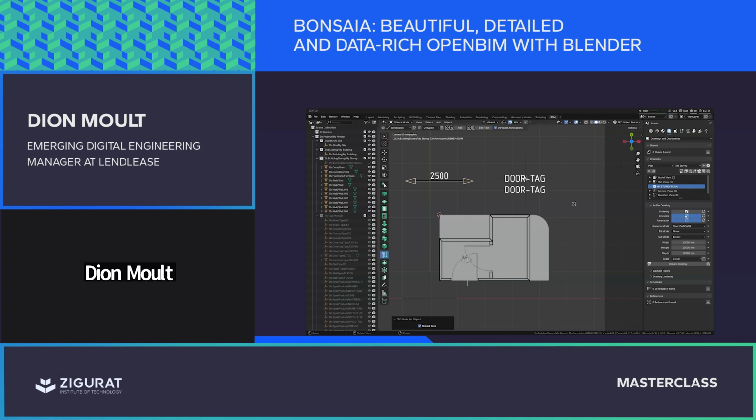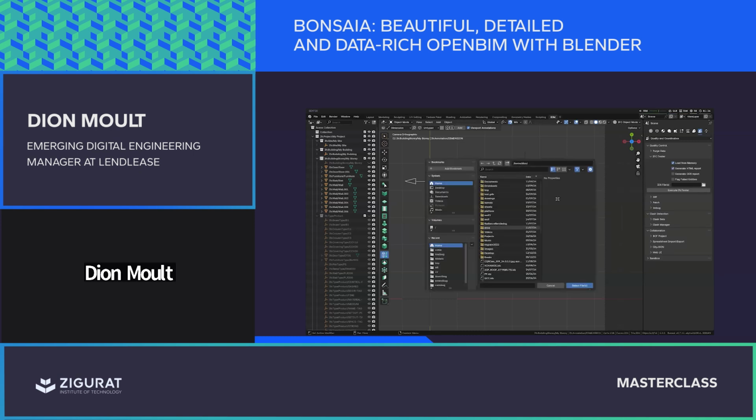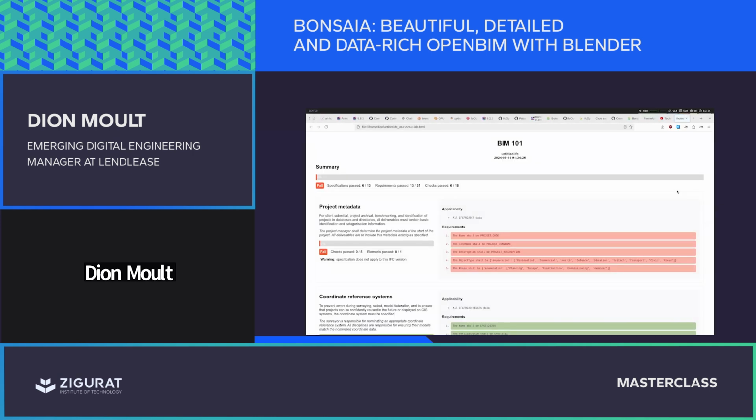For example, if we want to audit this model, I can jump over to quality and coordination, or use these tabs on the top. IFC tester. We can load a whole bunch of IFC files. For now, I'll just load the current one I have. We're going to generate an HTML report for it. And there we go. I have now run an IDS audit against my project.